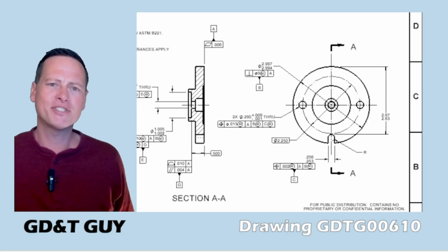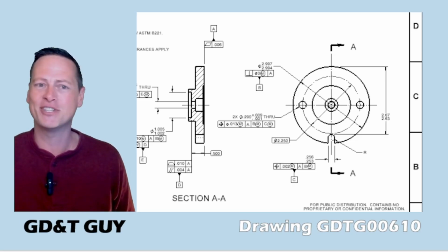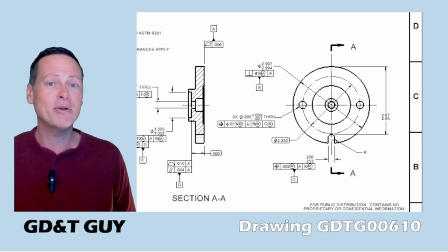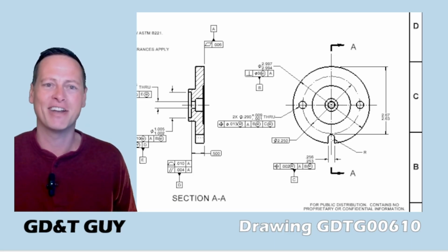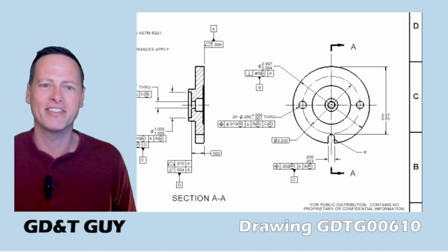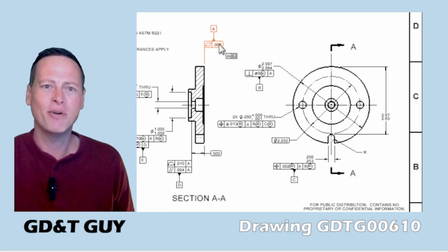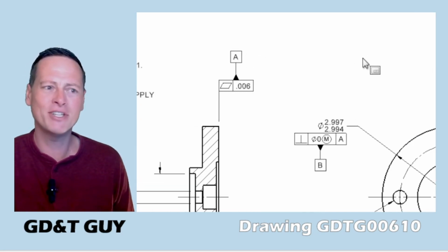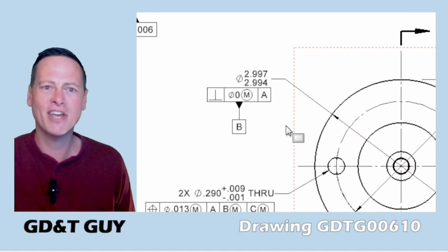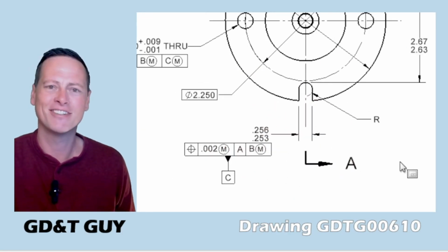We see this also in the standard. It looks a lot like figure 4-5. Hopefully you were shown something like this if you took GD&T training. Maybe you even have this on your wall chart. I know I've had stuff like this on my channel with an interface that looks a lot like this. And if we're thinking about 6DOF constraint, we are right here in our comfort zone. 3DOF primary datum feature, 2DOF secondary datum feature, 1DOF tertiary datum feature.